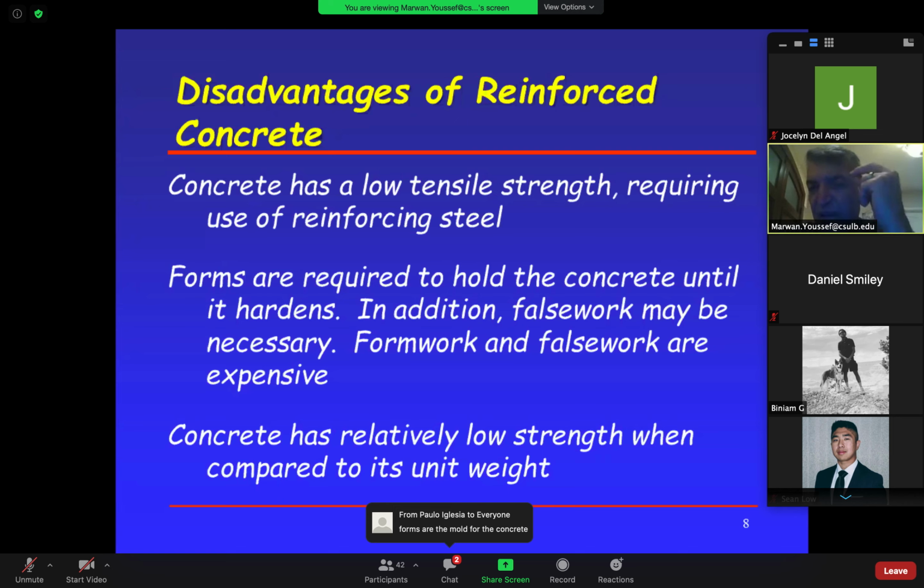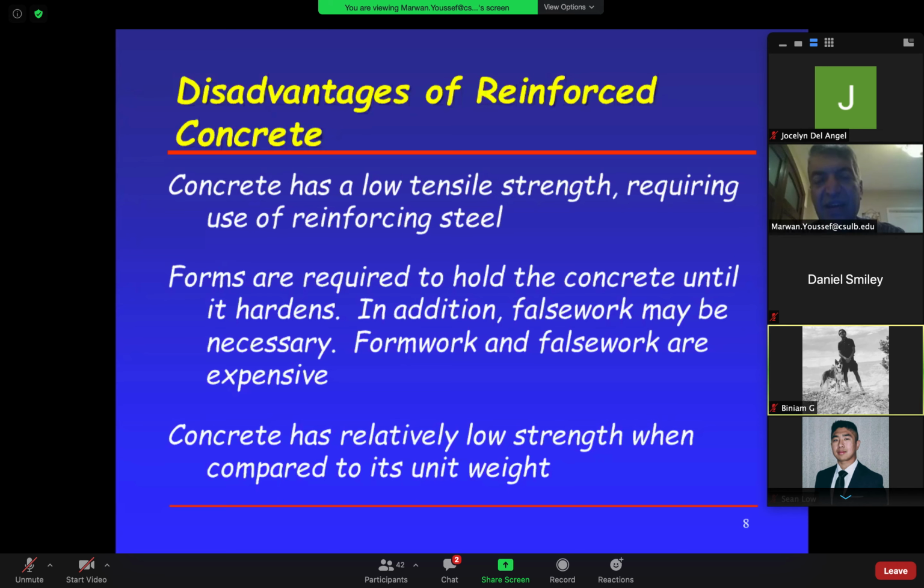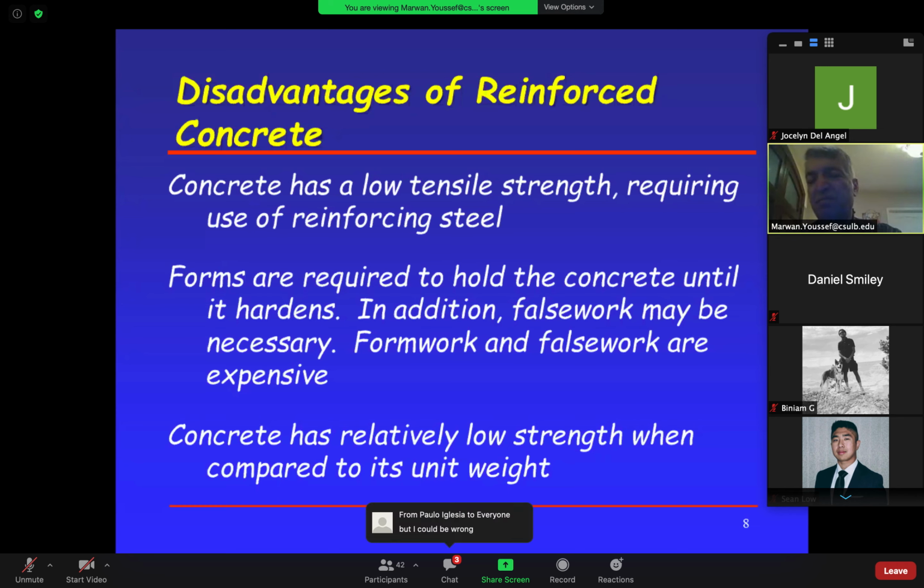This is how you figure how heavy the concrete is and what its density is. Can you imagine 150 pounds? That's the weight of a person, and it's only a 1 by 1 by 1 box, the size of a basketball box. So it's heavy concrete. If you put in a beam that is 30 feet long, typical beams are going to be about 16 inches wide, maybe 24 inches deep. Can you imagine how heavy that is? Very heavy. Okay? So that's what it says.